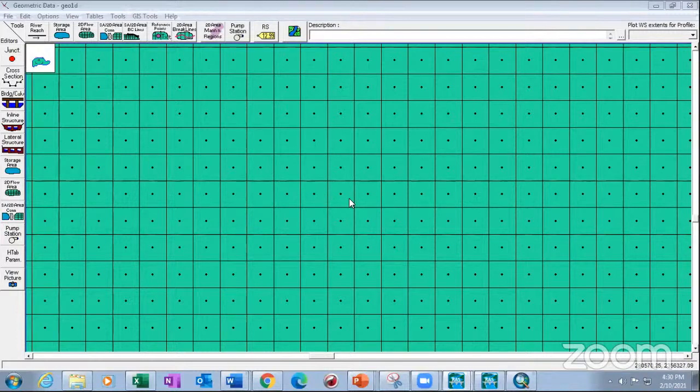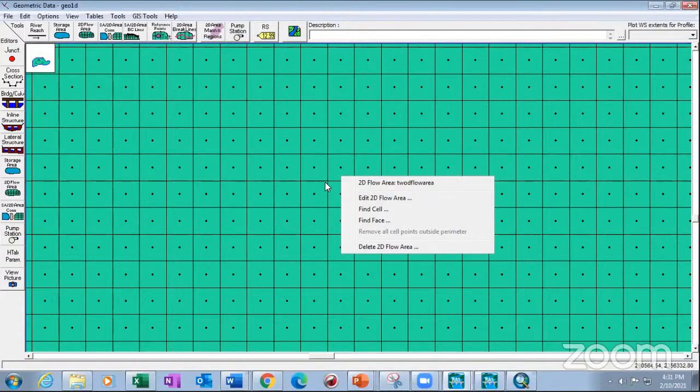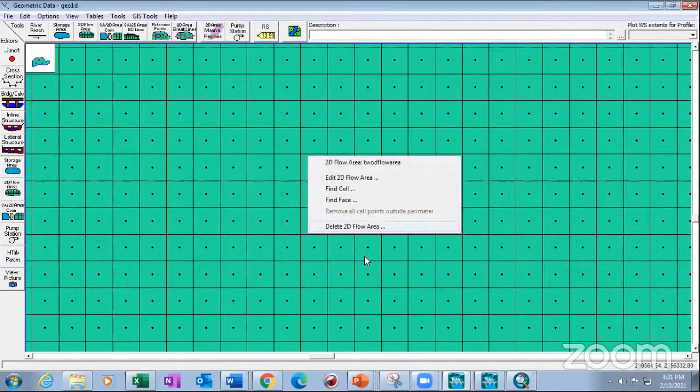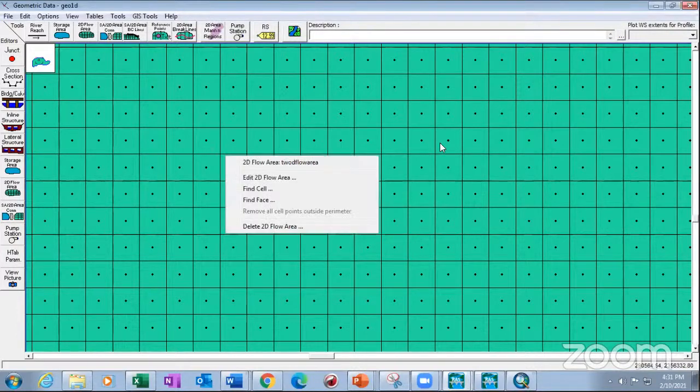Because this is a large area, 200 300 meters, the 200 300 dx and dy is too high. Generally it is not that much. For demonstration I am doing this; you can refer to some good research papers to understand. But in general, we follow the Courant number, and then we define how much dx and dy should be. So generally it comes around 80 to 120.